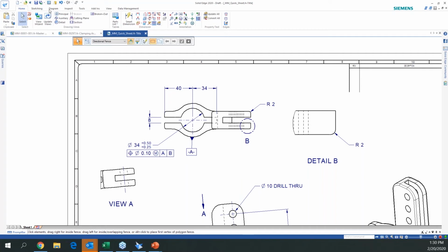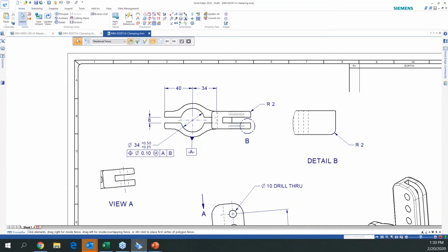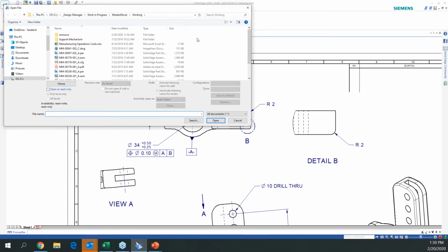So I'm using a data management tool. Remember, I can save this drawing. Here I'm literally creating my part, saving my part and my drafting right into the Solid Edge data management tools that I currently am using. So I can say yes to this and save it. Now I've saved that geometry, but I also want to open up something new, and I'm going to search my database.